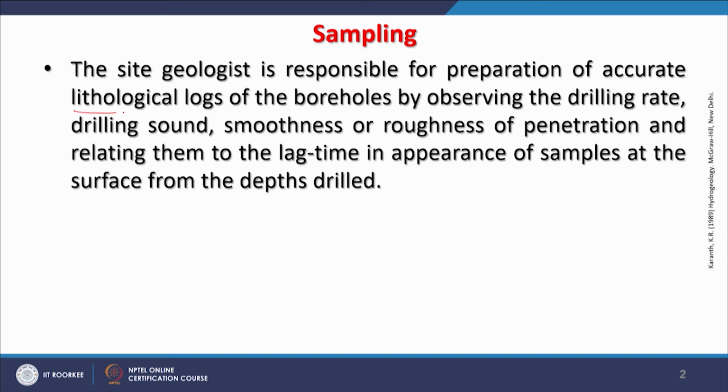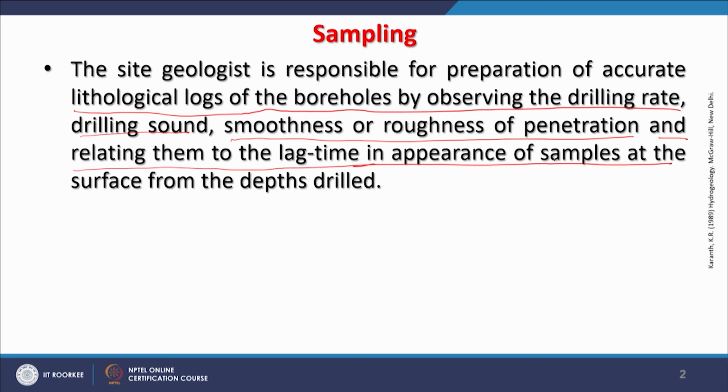A driller will keep recording information, observing the drilling rate and the drilling sound also. Expert drillers or a site geologist can assess, based on the drilling sound, what kind of rocks are being encountered by the bit at a certain depth, the smoothness or roughness of penetration, how fast it is going, what kind of vibrations are there, and relate them to the lag time in appearance of samples at the surface from the depth drilled. Depending on the kind of material being drilled, the time it takes to come up will also vary. So, this lag time is also recorded.